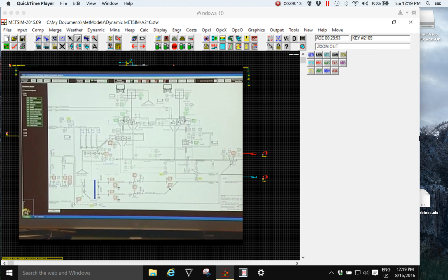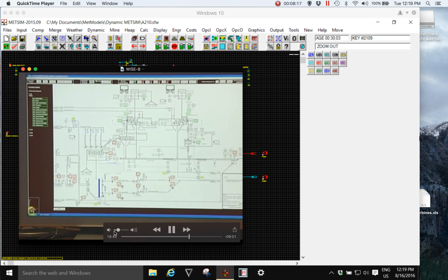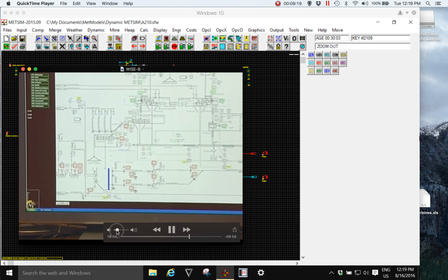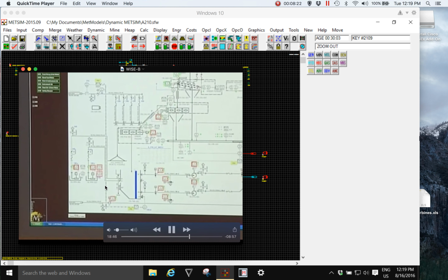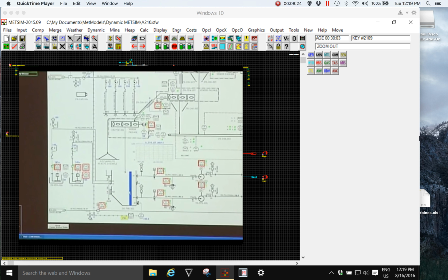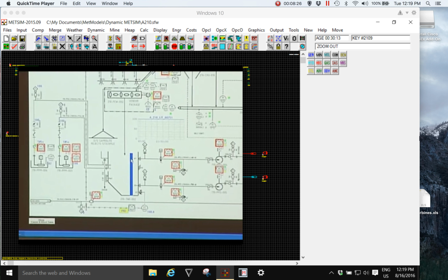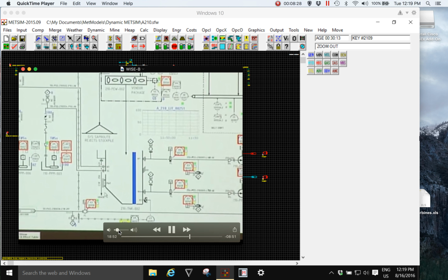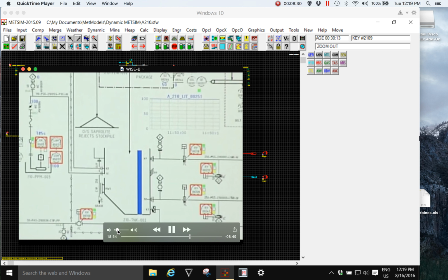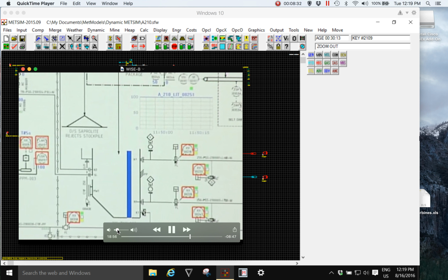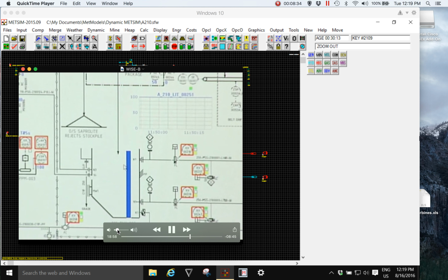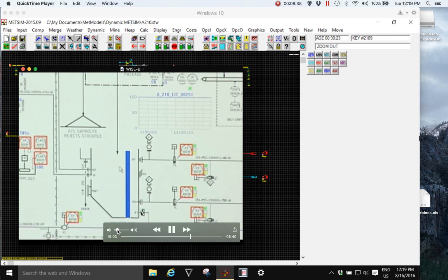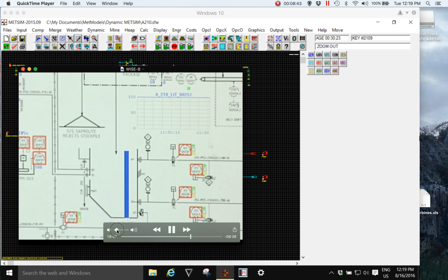Because I've been pouring water into this hopper, we can expect there are no pumps running, the suction valves on the tank are all closed, and therefore the level in the hopper is 100% and it will be overflowing. Now in a simple schematic like this, there is lots of information that you simply cannot see. It won't be shown on the control system because there is not a flow meter on the overflow. But if we wanted to see additional information...